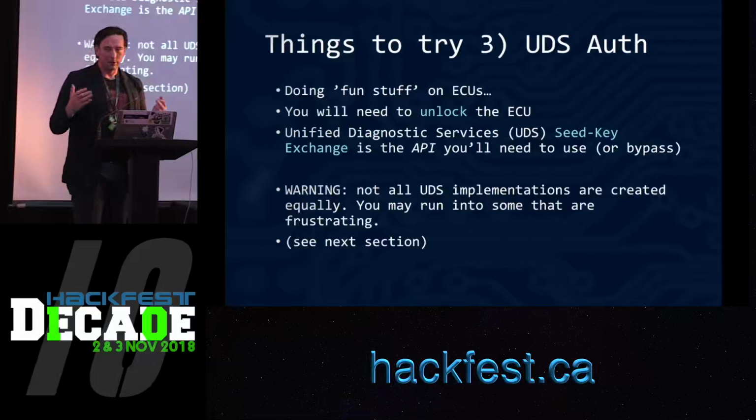So UDS is a diagnostics protocol. It also specifies a transport protocol. If you think about how TCP is built up out of multiple fragments on whatever medium it's being sent over, part of UDS is something called ISOTP, and ISOTP knows how to reassemble the really small CAN messages into a stream of bytes. So remember that UDS is now a stream-oriented protocol and not those little frame-oriented protocols. It makes things a little different. And pretty much all vehicle diagnostics in passenger cars actually rely on UDS.